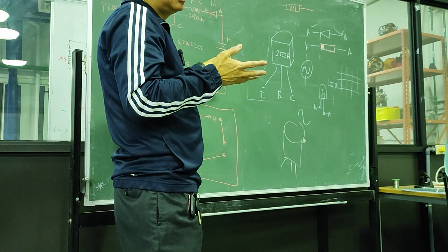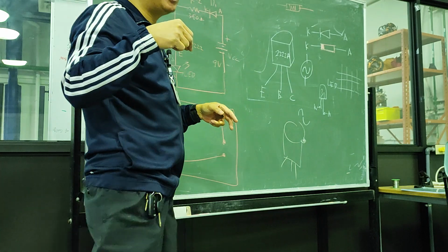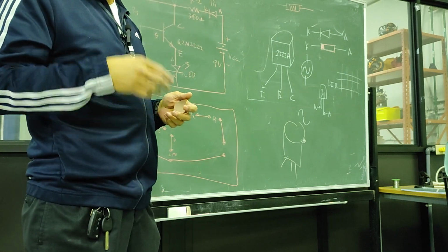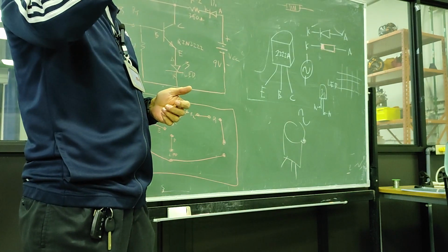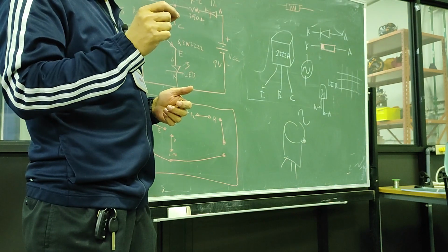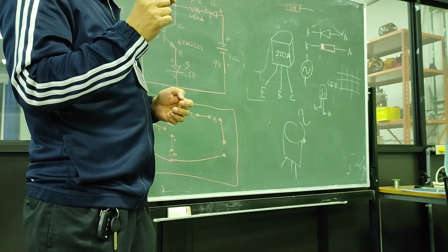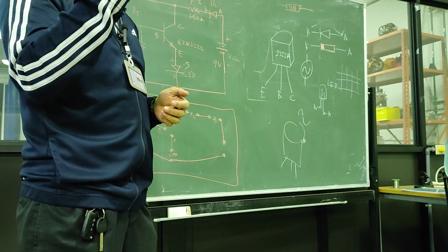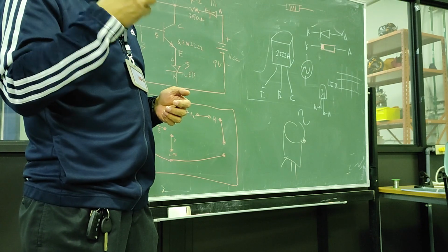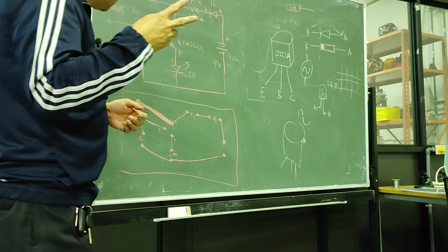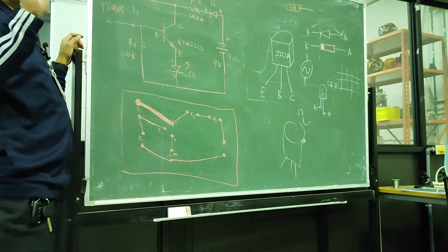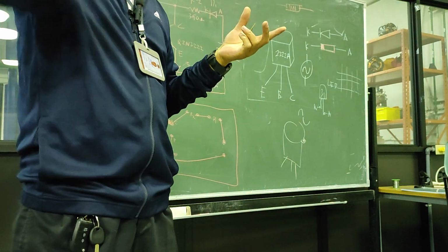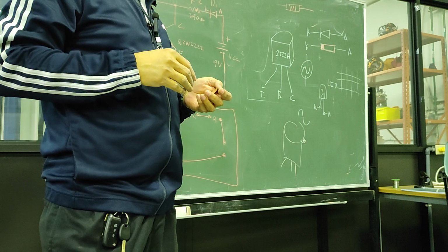One last thing. The battery is very important. There's a positive and a negative side. Don't reverse it. It will not work, or we will burn the component. Be careful with the positive and negative terminals of the battery source. Usually, positive is represented by red color and negative by black color for the wires. For the resistor, there's no issue, because there's no polarity. Even when you reverse it, no effect, no problem. It doesn't matter.